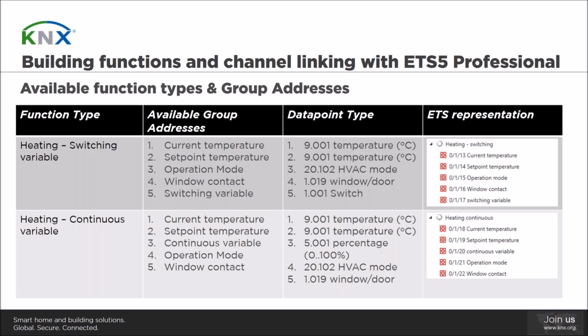While today, or even in the future, if you only have group addresses, then ETS does not have the semantic information to recognize that a combination of group addresses composes a specific function. When using the functions, ETS has all the semantic information to know that a collection of group addresses represents a building function.